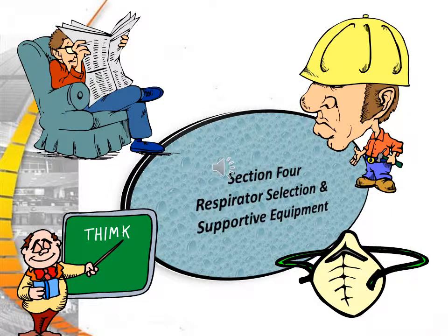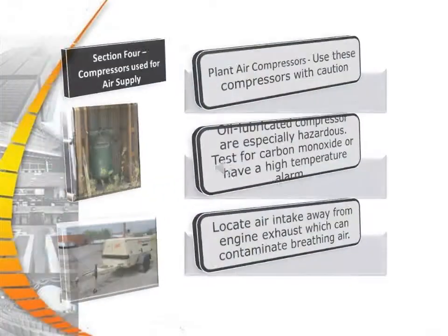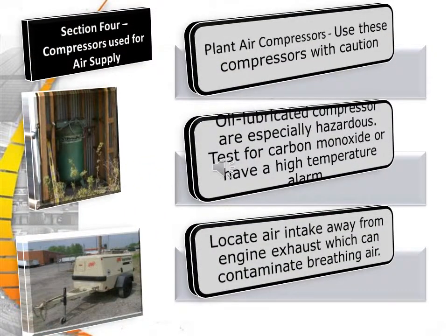Section 4. Respirator Selection and Supportive Equipment. Plant air compressors. Use these compressors with caution. Oil lubricated compressors are especially hazardous. Test for carbon monoxide or have a high temperature alarm. Locate air intakes away from engine exhausts, which can contaminate breathing air.